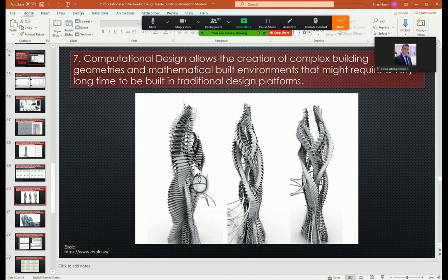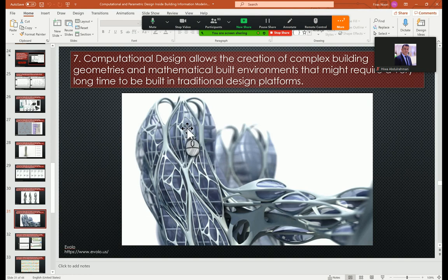And now Dynamo, or the computational design platform, can get you the detail for each piece of your model and how big it is and how you cut it and how you manufacture it. And it's even curved in 3D. It's not a pure projection for any specific surface, so you can make an elevation for it. So here we open the door for robotic design to make this type of complex building.